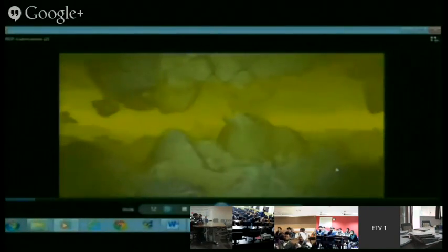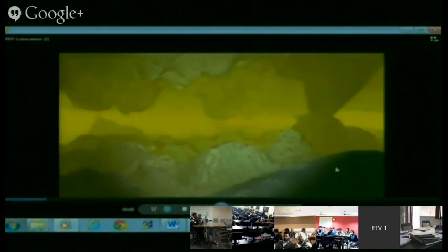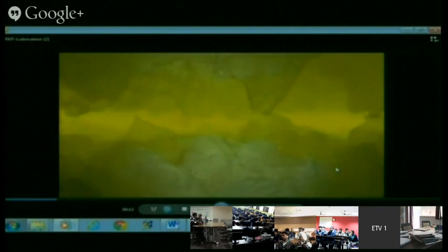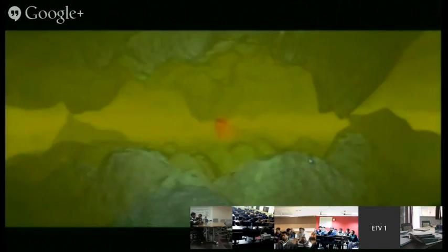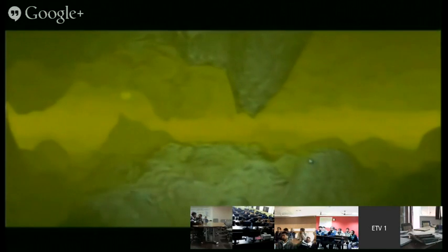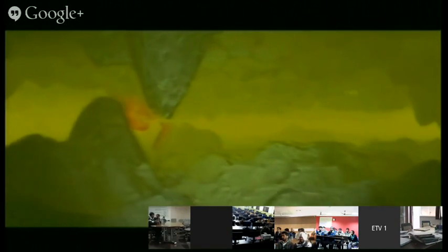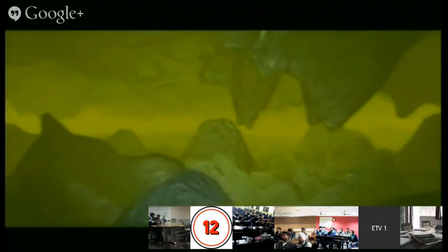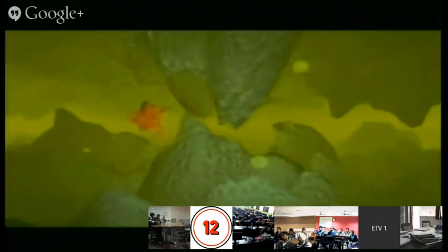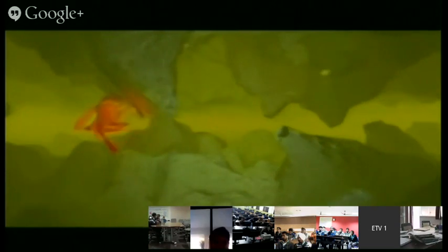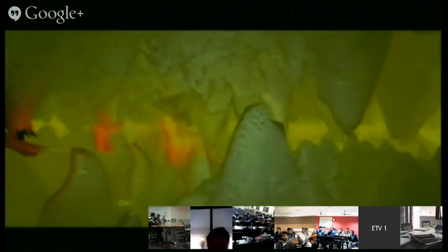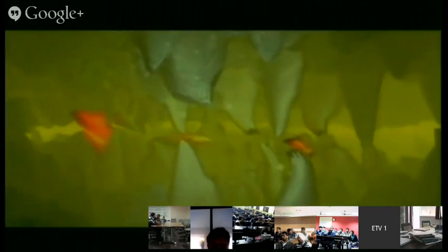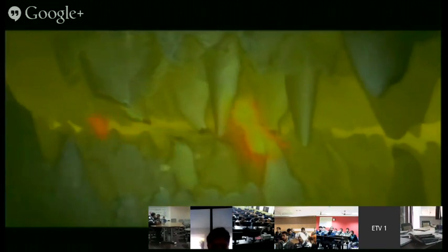Suppose one surface is a piston ring and the other is a cylinder liner. A lot of asperities are there, and lubricant is available. Contact is taking place asperity to asperity, then welding is taking place and debris is being created. The concern is that if the lubricant is not available and not separating the surfaces, then huge metallic contact will be there, or welding of the metals at various places, and in order to break that welding to have the motion, a lot of energy will be consumed.